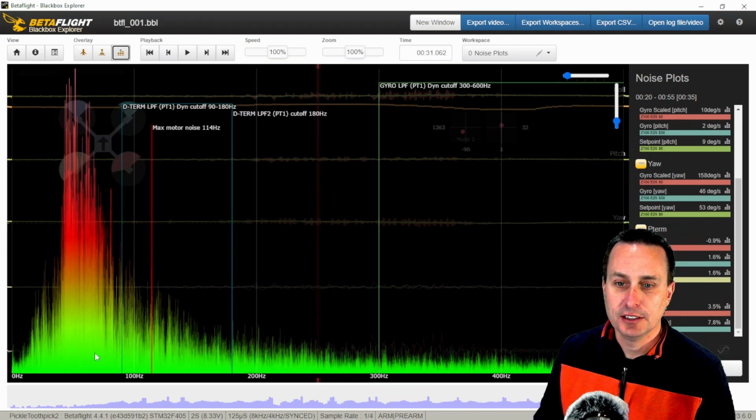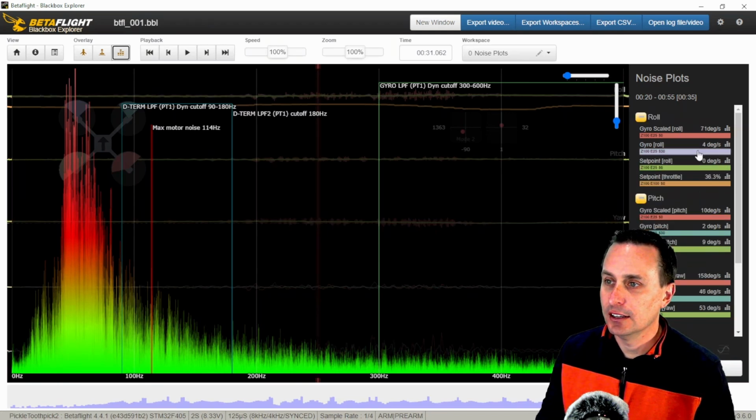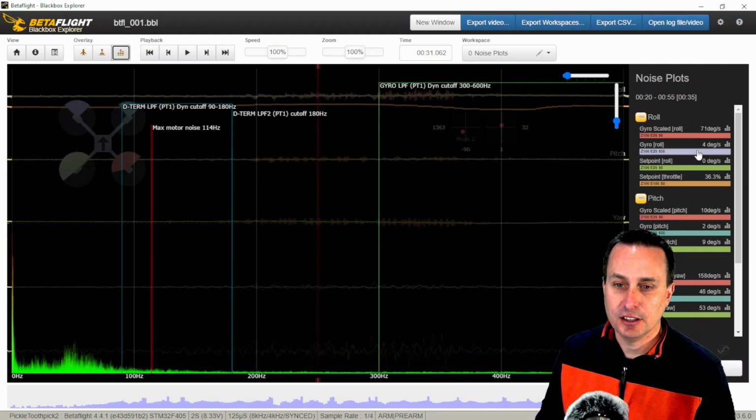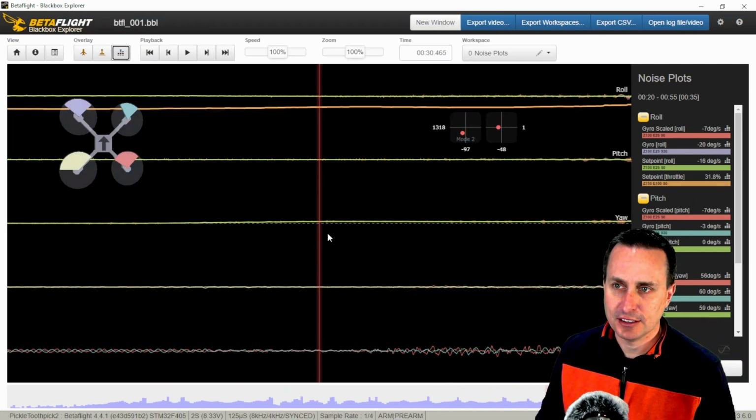but when I look at the D term, you can see this stuff. Look at that amplitude. This should be troughed out, and you should see vibrations up here, not in this zone. So that's bad. Go into here. You can see a lot of that is getting through. There's just some stuff happening at the low frequencies.